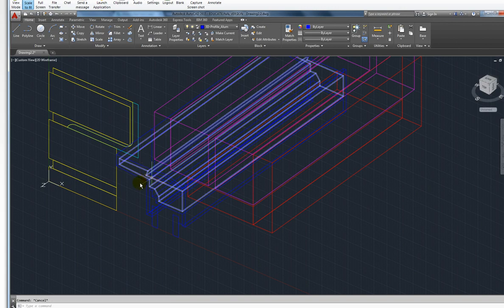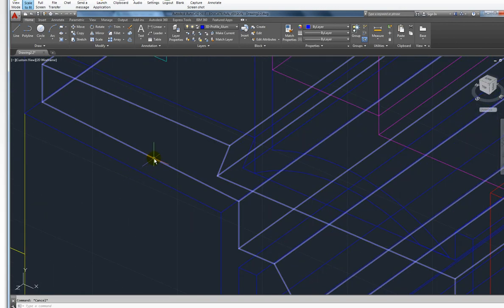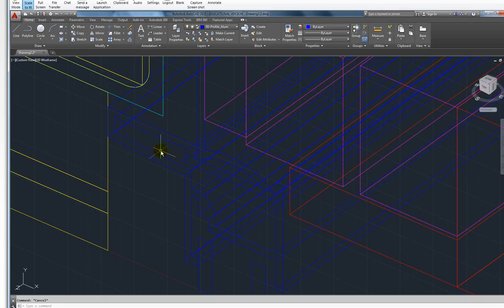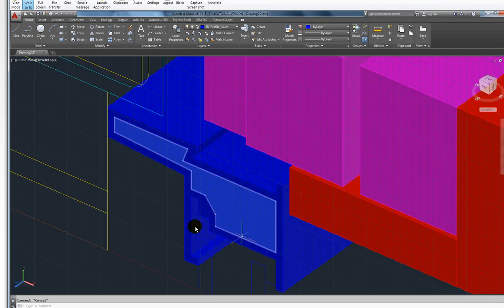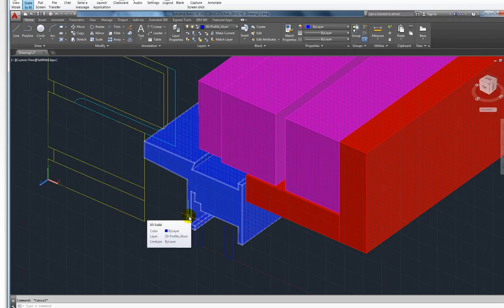So here I selected 2 at the same time, hoping that it makes a hollow shape. And what we'll see is it doesn't. So if I do shade, it just produces a solid and solid. All right. The command to use, this is a new command, subtract.